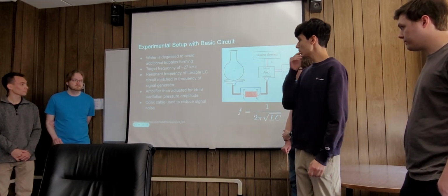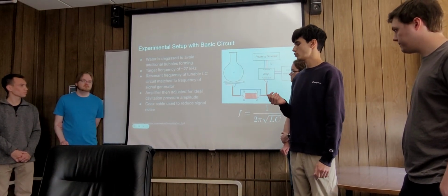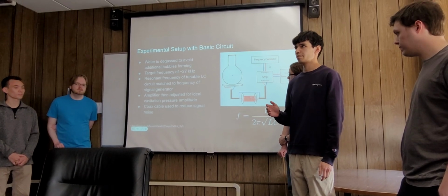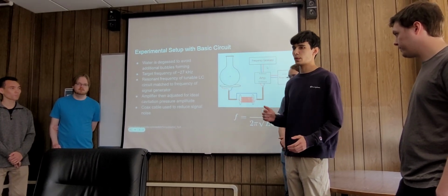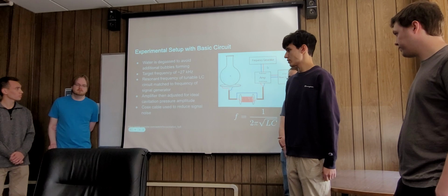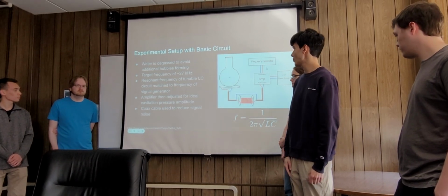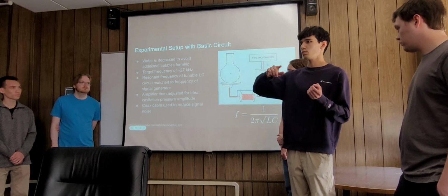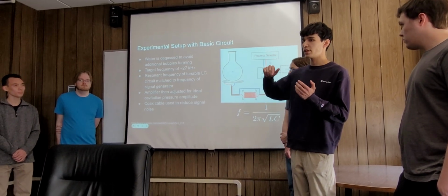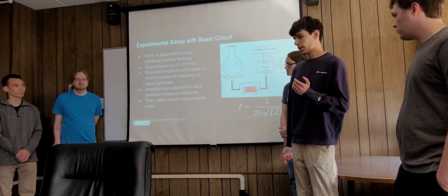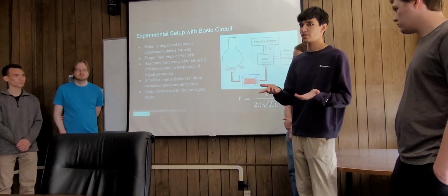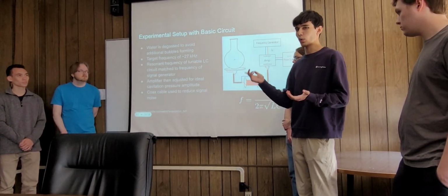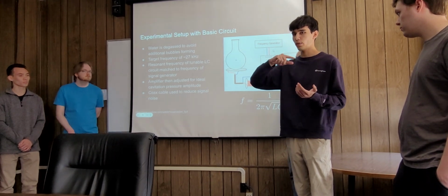The other difficulty is that these transducers actually require pretty significant voltages to be able to operate them, to drive them. So to fix this, we can take advantage of the fact that we're only really ever sending one frequency signal through our signal path. And that signal is the resonant frequency of the glass itself. So we'll have some 27 kilohertz signal passing through there.